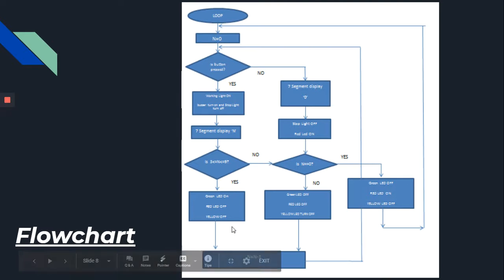Then we will proceed with checking the state of the number, which is n, and the number will reduce each second, like what the traffic light does. Afterwards, the looping will go back to 0 again. So let's go to the second option. If the button is not pressed, then the 7-segment will display a 0. So the stop light will be off and the red LED will be on.